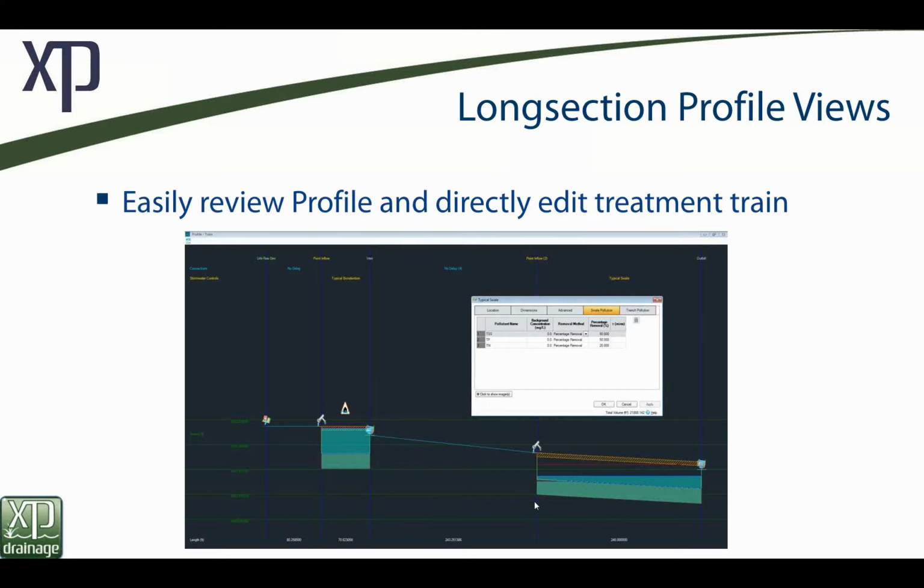And this swale, that was an example I mentioned before. This swale is filling up, but since it's at a slope, let's say 2% slope, this whole volume could never really be used, could it? So when this facility overtops, we aren't actually filling up the whole volume. That's something that we couldn't visualize or easily understand without looking at a long section. And we'll see this long section. If I want to update something, move it, I can update these items directly within this interface.